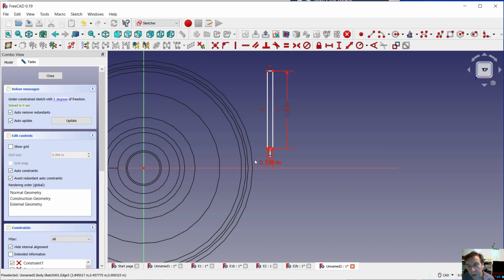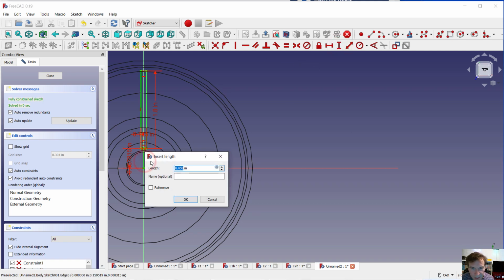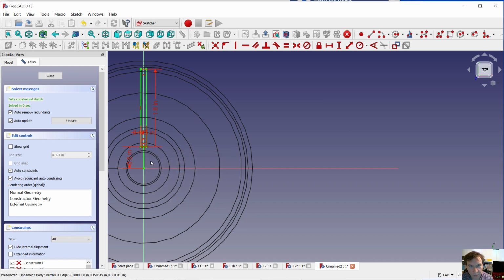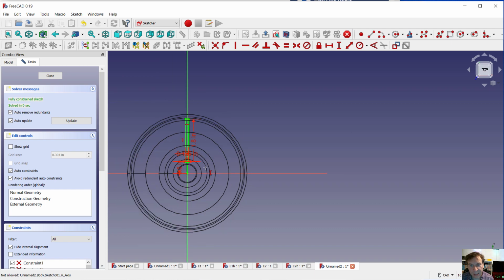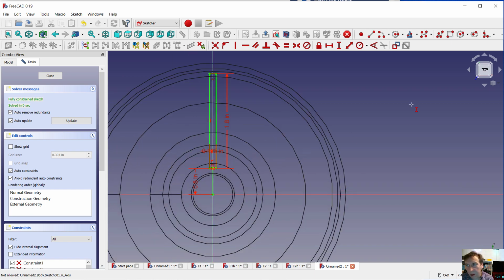And now what you're going to see here is I'm going to go ahead and let's go with coincident. Select that little point at the end of that line to this point, and it will center it for us. And now let's add one more dimension on that line there. And I want you to put in 0.5. Okay, and that should position it so that it's in the center there of our geometry. And let's go to isometric now.